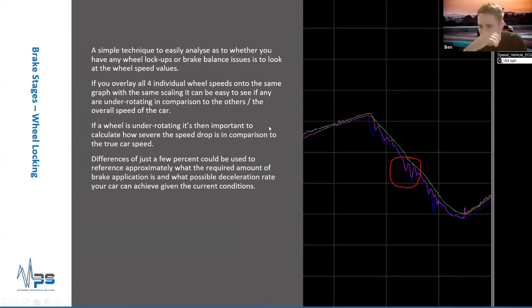Generally, it's a big generalization, but a tyre will keep giving braking grip, keep giving braking grip, and then it'll have its peak and then it'll quickly drop off and lose grip. At this point, we can visualize that because the wheel will start momentarily locking. So as it loses grip, the wheel will start to lock. The brake's more powerful than the grip the tyre's given, and we can visualize this.